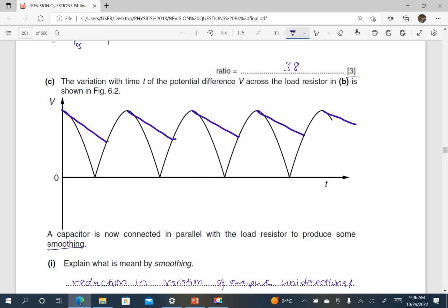So you draw starting from the peak. I don't know, my mind might not be very exact at the peak because of writing on a computer. So for the charging process, you draw the curving parts. Just pass the pencil there so that it appears as if it is bold. So that is charging, the other one is discharging. So charging, discharging, charging, discharging. That is the smooth voltage. That is the output of the smooth voltage. These should be ending at the same level.